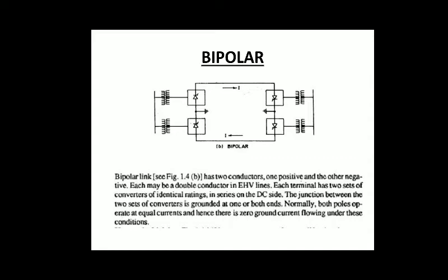So the current is rotating through this circuit, and in this case the wire is grounded as in the monopolar HVDC link, but as we are getting a closed loop path of our own, it is better to say the current is not using the ground for return because it has a closed path already.